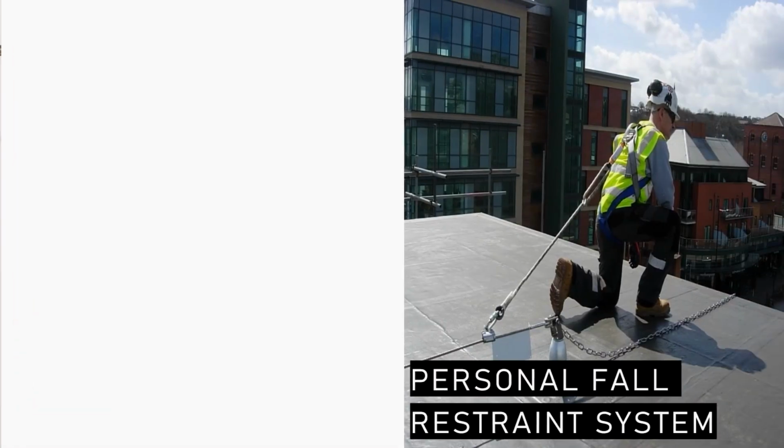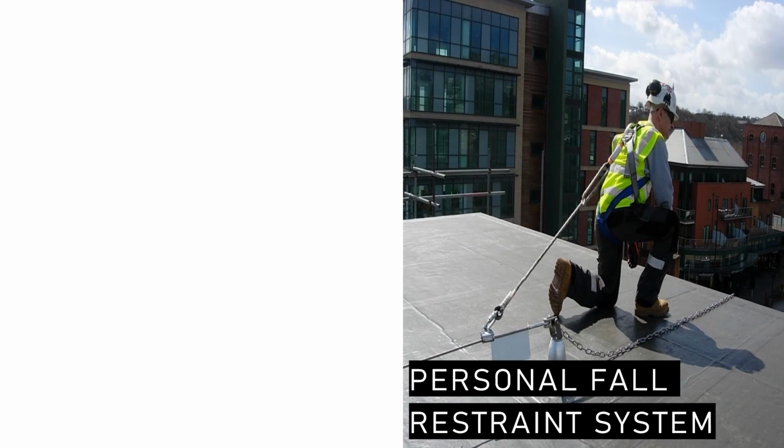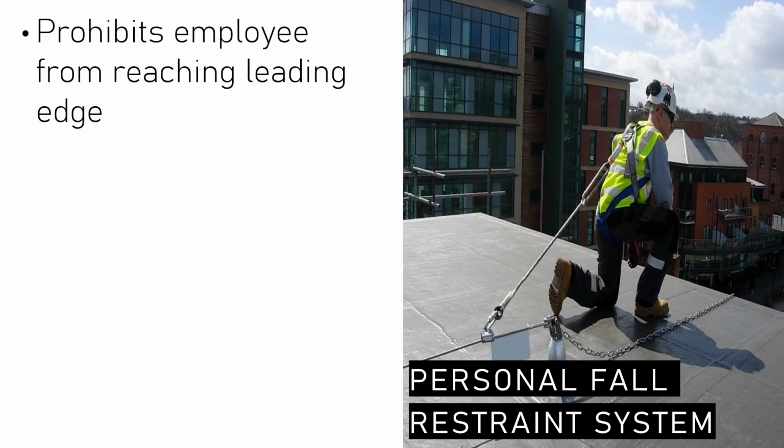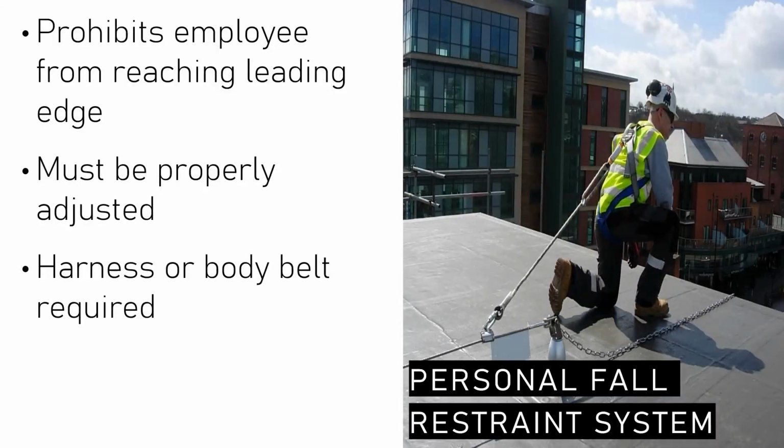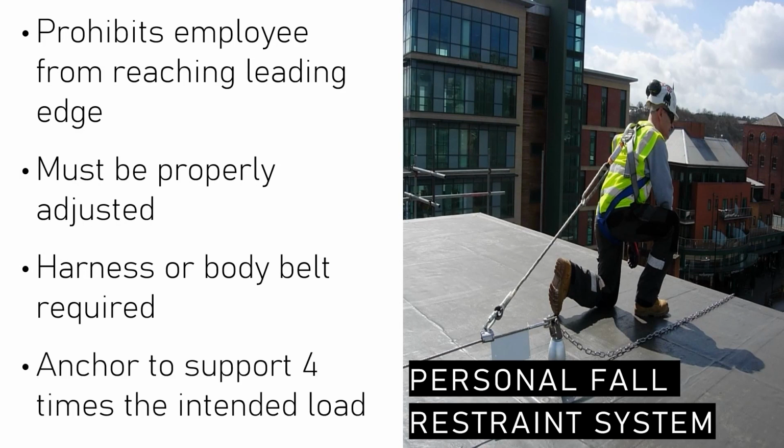A personal fall restraint system is set up so that the employee cannot reach a leading edge. The fall restraint system needs to be adjusted properly so there is no way the employee can get past and fall over the leading edge. A harness or body belt is required with this type of device, and the employee needs to be anchored. And the anchorage point must support 4 times the intended load.